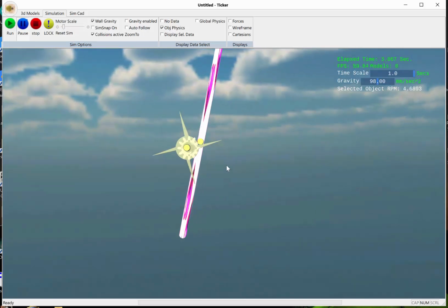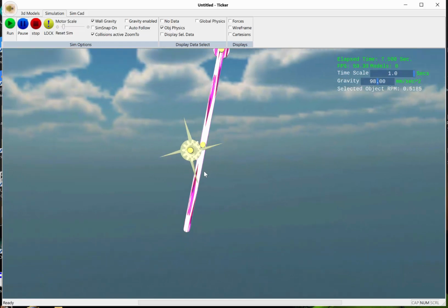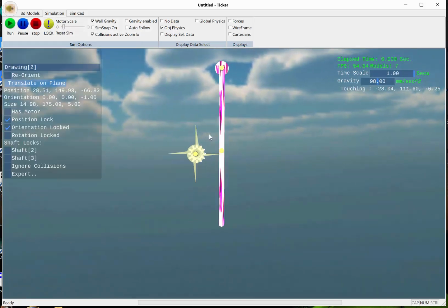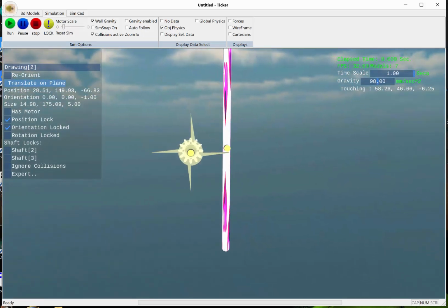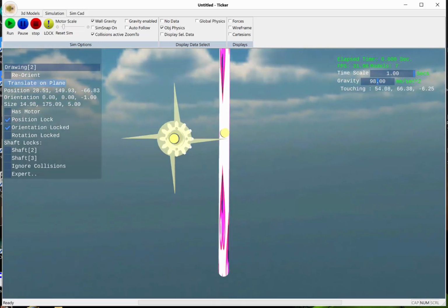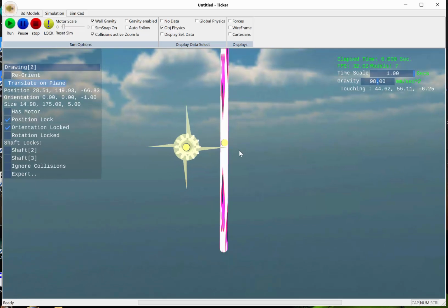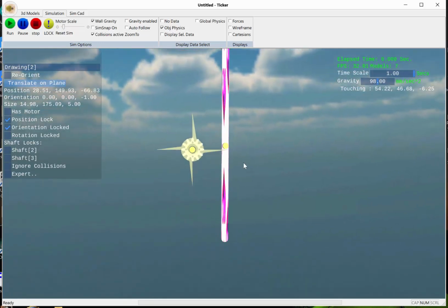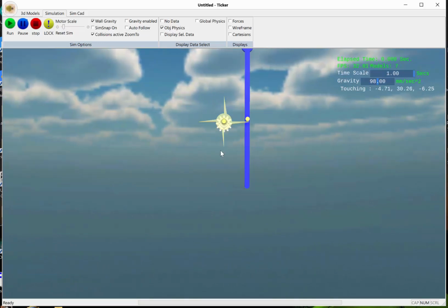And now you'll see when the object comes up and hits the pin, it just pushes it inwards. This is something I guess we could expect because it's not likely that you're going to get a perfect hit on this pin. As you can see, even when I drew it, I placed it just a little bit high, which means that when it comes up, it's going to hit this at a slight angle, which will cause this to sweep inward. On an escapement, you want to get that as exact as you can to 90 degrees on that plane.